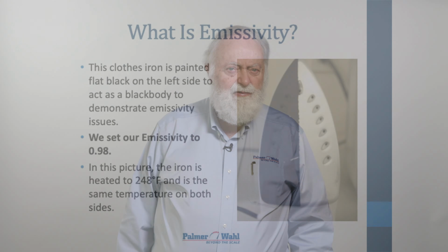As the temperature of a target increases, the emissivity will start to change. So for instance, an 8 to 14 micron unit, which measures anything within the ambient temperature you live in or ambient area you live in. If you get above a point of, say, 1200 degrees, the emissivity of your target begins to change pretty rapidly, so you're not going to get a good reading with that spectral range at those high temperatures.